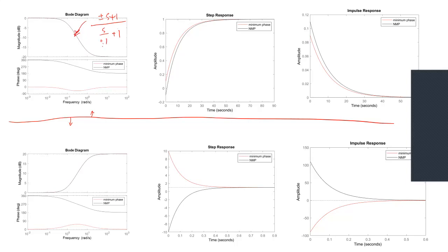Because you will go to the lag first. So this is like 0.1, okay? Then this is 1, this is 1 here. This is 0.1. So this 0.1 will correspond to this point at 45 degrees. So this is my minus 3 dB in here.